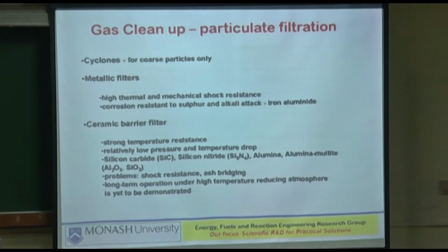Both cyclones and the metallic filters will tolerate high temperature. A metallic cyclone, of course, if it is refractory lined, temperature is not an issue. And usually it is refractory lined.